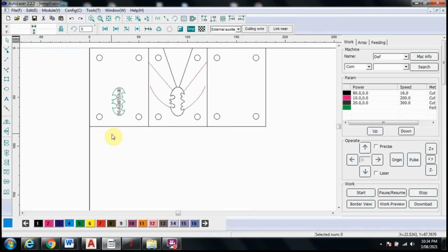Okay, so the first thing we're going to do is change our engraved part, the bit that we want to have engraved, to the layer that I have set up for carving, which for this one is layer 10. You'll see that those two layers have disappeared and been replaced by this one purple layer, which is my layer 10. And I have those settings already set to the right options.